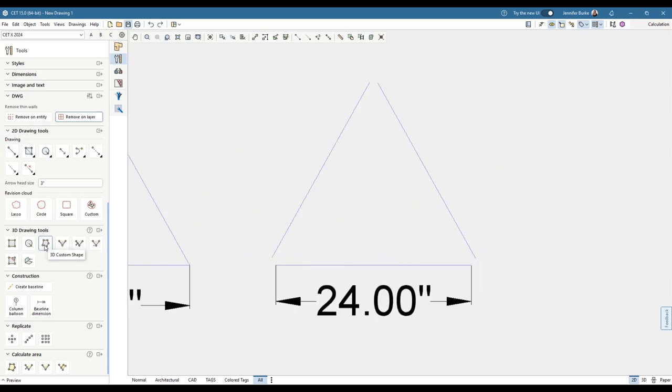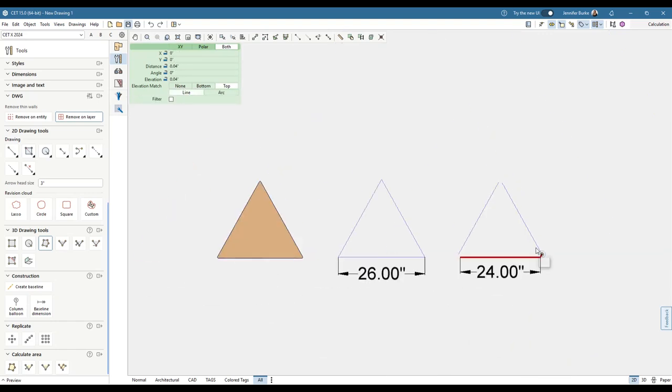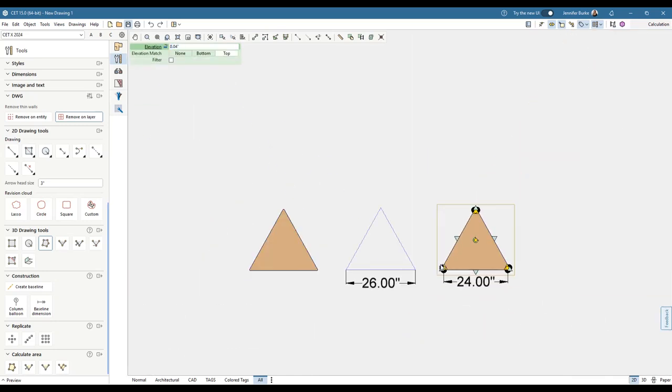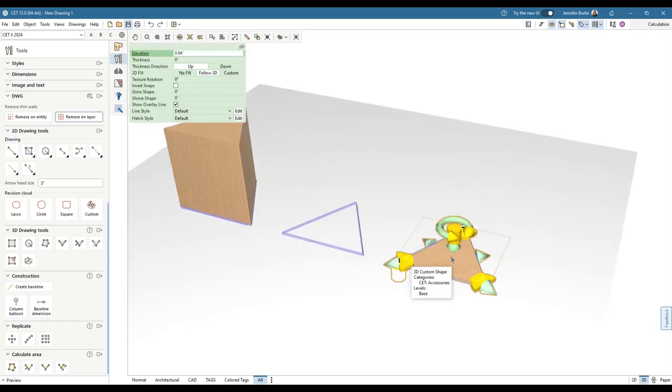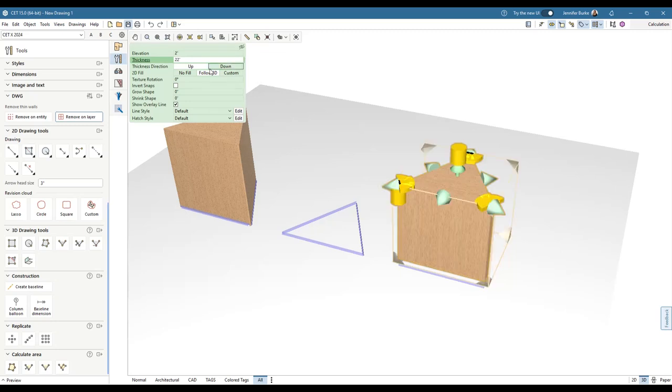Now we're going to just simply trace over that help line by only using the straight. So we're not going to use the curve this time. So we'll trace over this, and we're going to cut back here, trace, cut over, come down and cut back. So what that looks like in 3D is another triangle. So this time we want to also create that picture frame. So let's do 2 inches above the floor as the elevation, so you'll have your picture frame banding at the bottom. Same thing on the top. So we have a total of 26 inches high. Let's do this one at 22.